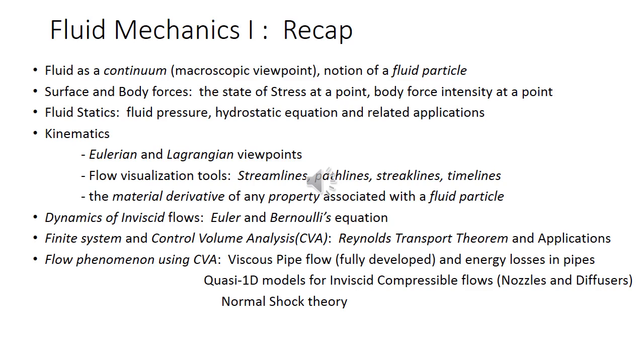And from the point of view of atoms and molecules, though we are not considering them or their effects, we can say that the origin of these forces lies in the exchanges of momentum at the atomic and molecular level through the surface, and the force potentials that exist at the atomic level. Those momentum exchanges through the imaginary surface in the fluid, and the force potentials, can all be lumped up and just talked about as a surface force on an imaginary surface in the fluid continuum. So this is what a surface force is.